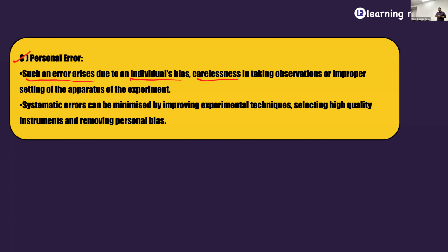Or sometimes there is something called parallax error. In the sense, if you need to look at this reading, you cannot see it from the top. Due to refraction or something, you will not be able to see it right. So you need to keep your eye exactly straight and try to coincide. If possible, keep a small toothpick or something like this, the thinnest device, and try to take the reading; it will be more accurate, if you want those kind of precise readings. That depends on what experiment you're doing. Are you able to understand what I'm trying to say? These are called personal errors.